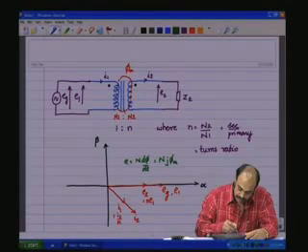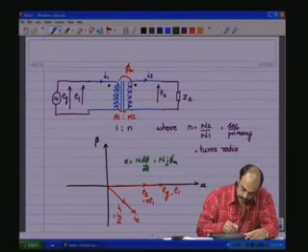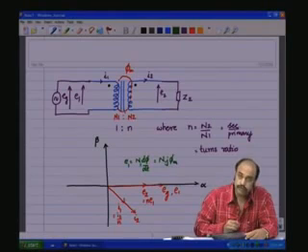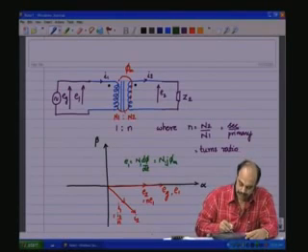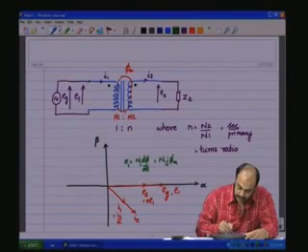Now, the induced EMF E is in this direction, this is the E1 direction. If you are taking the induced EMF across the primary, it is N1, phi m. So, either E1 or E2 one could take, and we know that they are in phase and they are along the alpha axis. Now, phi m lags E1 by 90 degrees because of the j operator.